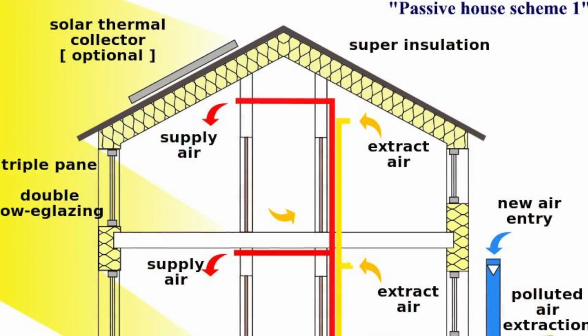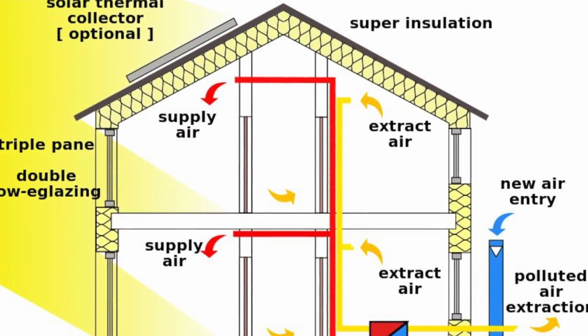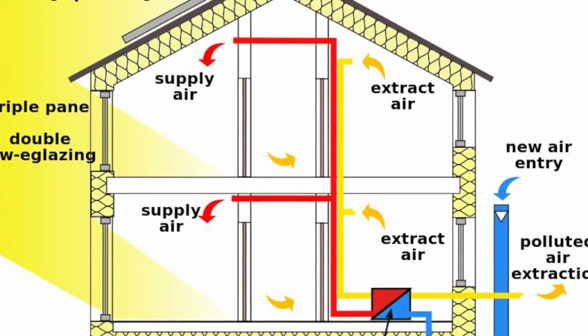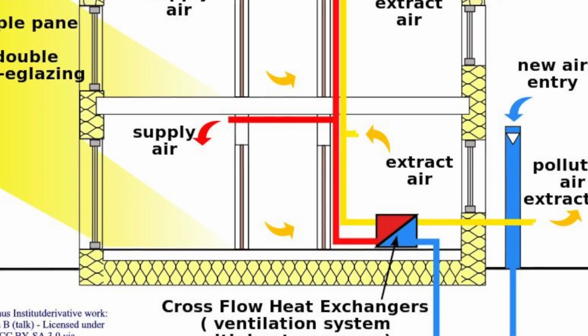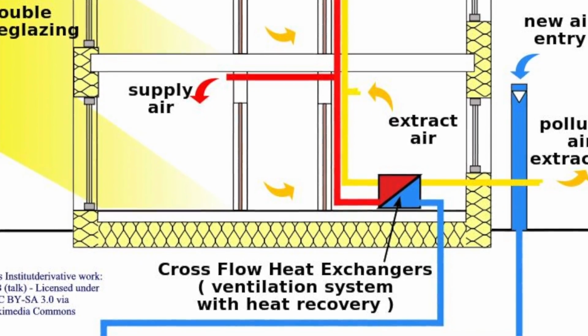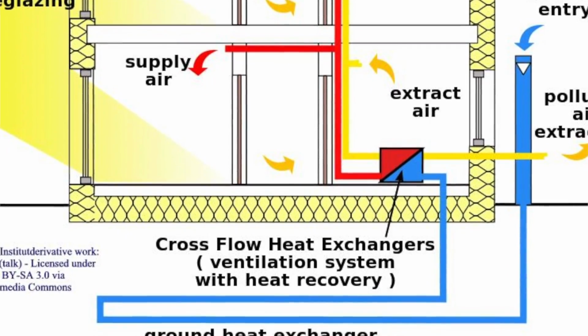It's not so much about some of the technologies that are applied to the concept, such as super insulation, low U-value windows, and heat recovery ventilation. Those are all technologies that are being applied to buildings now. However, they went a step further to get the numbers that they said were possible, where you could really start thinking about eliminating the heating and air conditioning, except for dealing with ventilation. It affected lifestyle a little bit.